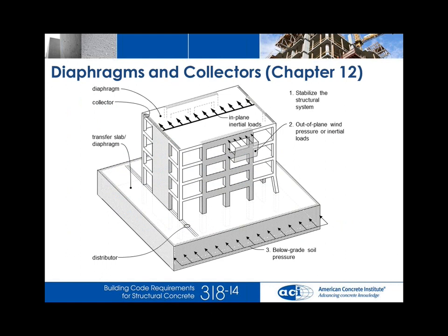So any building that has subterranean levels is liable to have soil pressure that has to be dealt with. And in this instance, the external basement walls pick up this pressure, generally transfer it vertically out of plane to diaphragm elements that are in the foundation or at subterranean levels or at grade level. And then those elements transfer these lateral forces either to basement walls that are in plane or other internal elements that resist those soil forces.